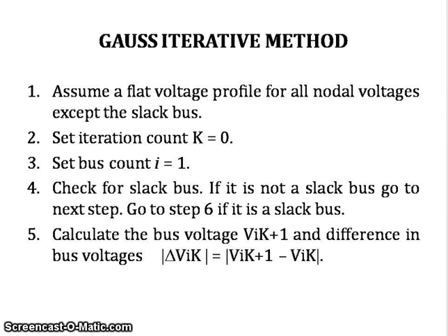Because they are nonlinear algebraic equations, iterative methods are popular for computing the solution. The first method is the Gauss method, the second method generally used is the Gauss-Seidel method, and another is the Newton-Raphson method. Apart from these, there are a few more methods like the fast decoupled method, and ANN, artificial neural network methods are also possible.